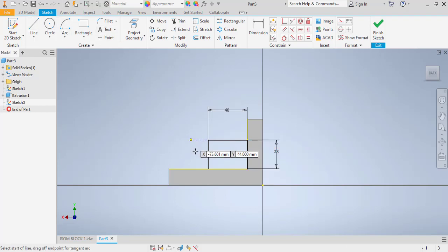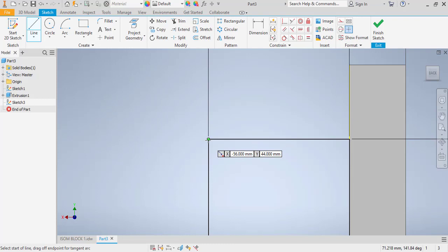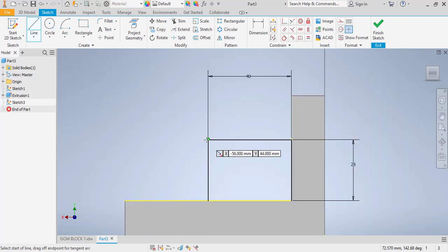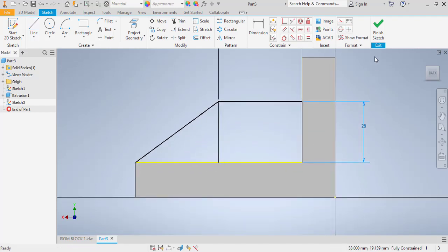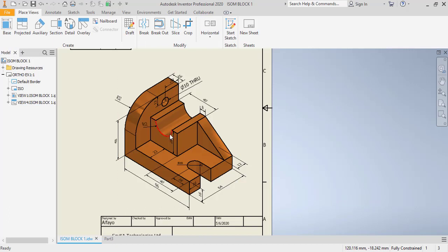And finally I want to draw this line from that corner. You can also, it can snap. Let me, yeah, it just snaps to that point, and that one, and I'll close it. It's also fully constrained, so I don't need to draw that line even. Okay, in this case there is another part here, the curve. This part, this curve is R12.